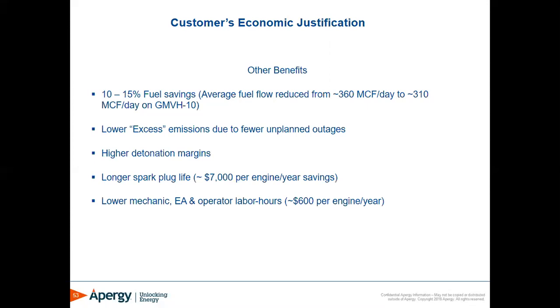Before they had the auto balance system, they were doing manual balancing. So they had an analyst that would go out there with an analyzer. He'd collect peak firing pressures, tweak the manual valves, open or close, take another round of pressures, tweak the valves, do that all day until the engine was finally balanced. So the auto balance does that continuously.